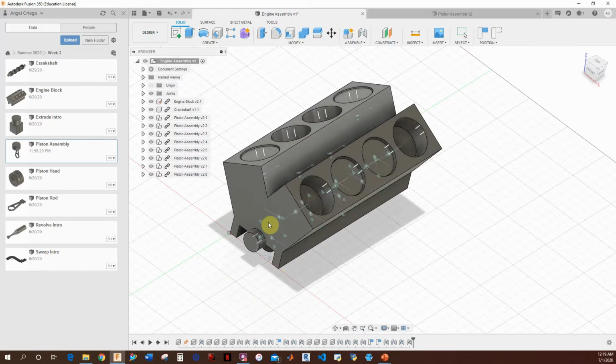So what this allows is for an engine that's actually balanced. Otherwise, if I were to have all of the pistons on the left go up at the same time and all of the pistons on the right go down at the same time, then the forces acting on the engine would make my engine rock back and forth because it's unbalanced, right?